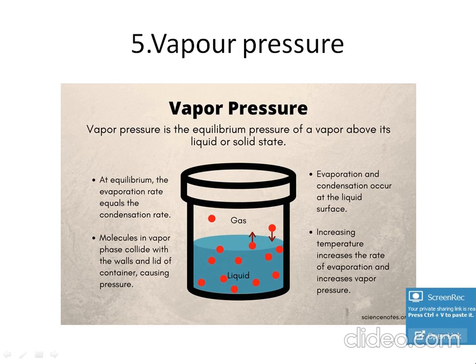The molecules on the surface of liquid are in highly excited state, and these molecules, by taking energy from the molecules below, get evaporated. The air above the liquid can absorb these vapor molecules only up to saturation. Once saturation is reached, the number of molecules leaving the surface of liquid on evaporation becomes equal to the number of molecules condensed back to the surface. Such a condition is known as saturation or equilibrium condition.